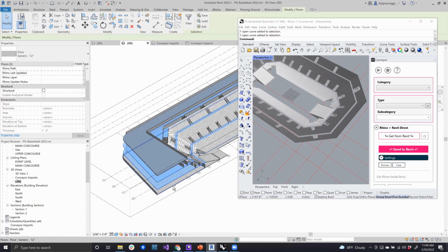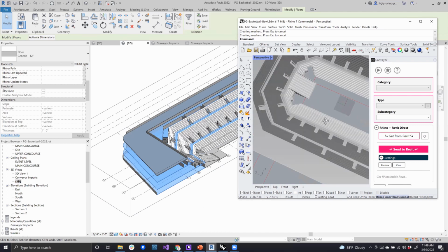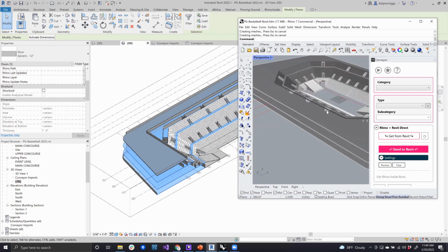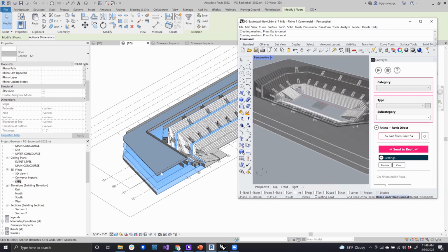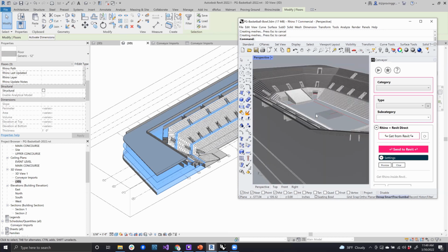We've got a couple of floors here inside of the Revit environment, and you can select those and say, okay, let's get those over into the Rhino environment as well. And that will then create those floor objects. So we can start to mirror these back into Rhino as reference points. Maybe you need to bring Revit geometry over into Rhino for, again, the coordination exercise, ensuring your bowl is lining up with everything as you're designing it here.